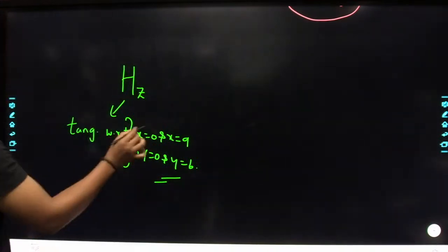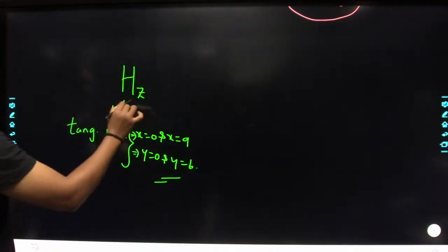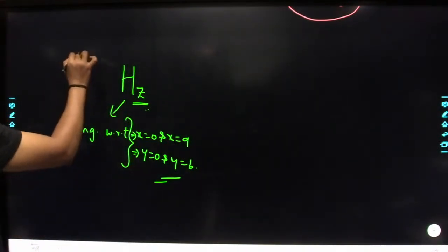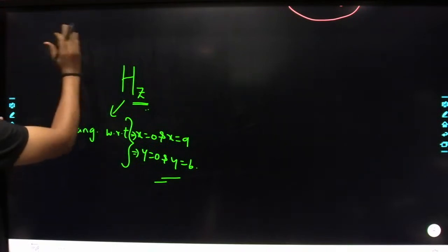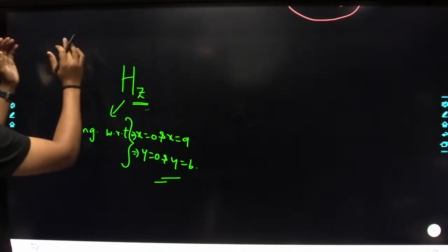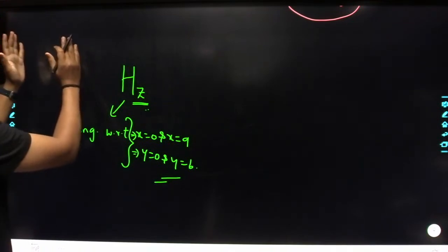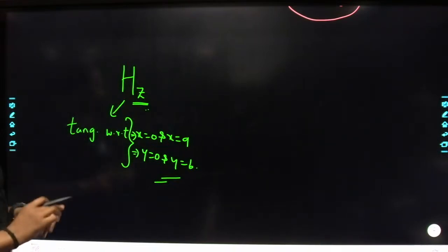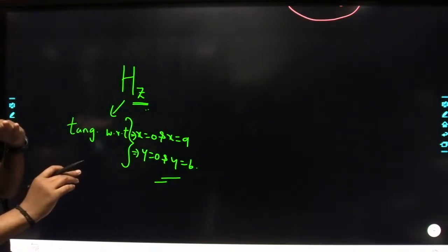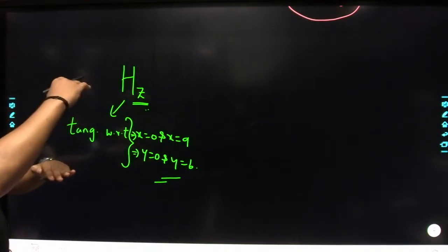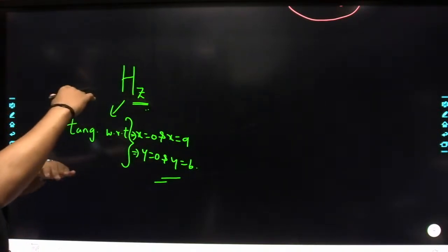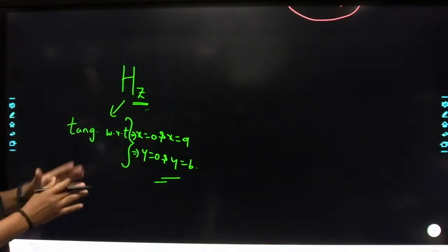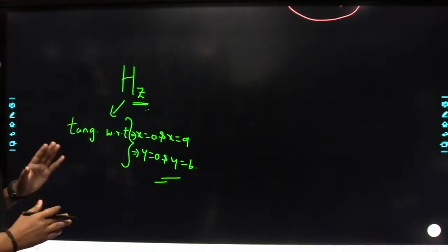Along x, the z component acts as a tangential component because you have perfect conducting interfaces at x equal to 0 and x equal to a. They are nothing but yz planes. With respect to the yz planes, the z component behaves as a tangential component, and you have two more conducting plates at bottom and top. With respect to these two conducting plates, the z component also acts as tangential. So with respect to four conducting plates, it acts like a tangential component only.